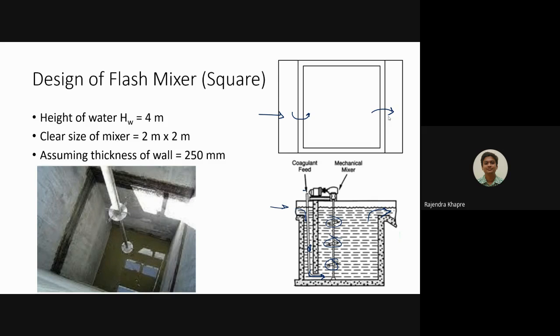Because you see, the shape is going to make a lot of difference as far as the behavior is concerned. Because in the square shape there will be a proper bending, and in circular shape there is no actual bending, there is a hoop tension. Okay, and for hoop tension only steel is required. Here bending also steel is required, but the magnitude of bending moment which is generated in the square shape or even in the rectangular shape, it is on the higher side. That's why you will find most of the time circular shapes are preferred over the rectangular shapes. Okay, that we will see.